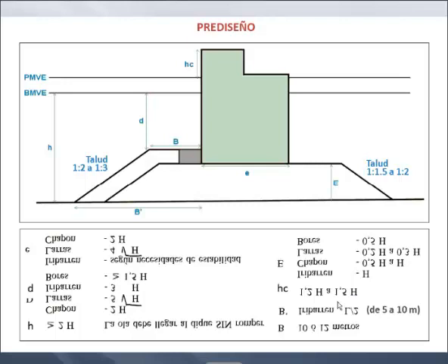Well, I will say, in the non-Japanese engineering world, a vertical structure fights against the energy by reflecting the energy. But to be able to reflect the energy, you need enough depth. In Japan, this type of structures are made in shallow water, so the wave enters and attacks the structure broken. And if it is broken, it cannot be reflected. So that is a third type of structure.